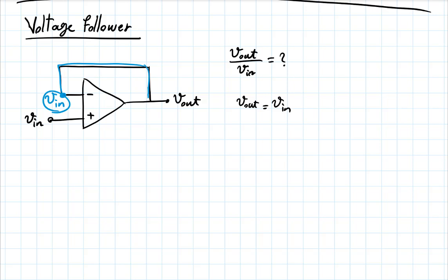Absolutely. You would also call it a buffer. It provides isolation. Whatever you connect here, this Vin. Now let's remember what you have in the back of your mind. This is what you have, right? Something like this. And that might come from any number of things. Maybe this is the output of a small, tiny circuit that cannot provide a lot of current.